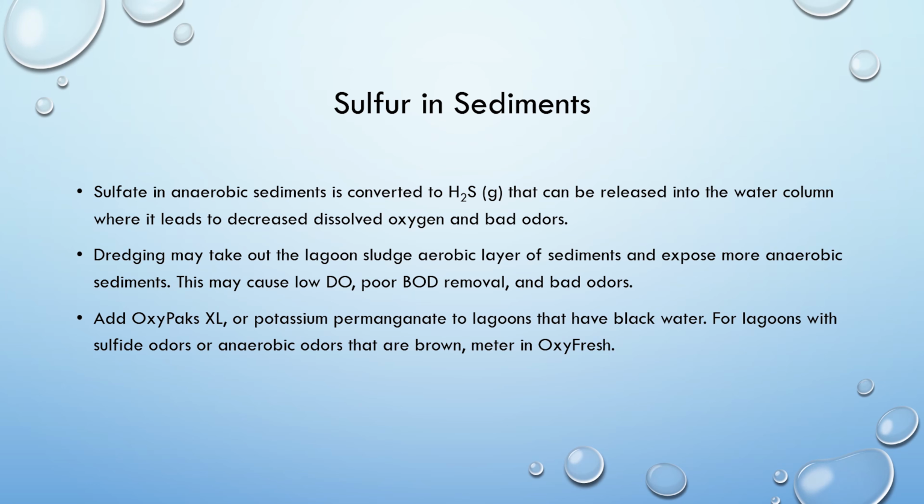Dredging may take out the lagoon sludge aerobic layer of sediments, and that might expose more of these anaerobic sediment layers. This may cause low DO, poor BOD removal, and bad odors in the lagoon. And it is necessary and beneficial to dredge a lagoon that is filling in with inorganic sediments. However, just remember that in the short term, it can release anaerobic nutrients, possibly toxins, and probably lower your DO. However, sometimes it's the only thing you can do to really recover your lagoon volume capacity.